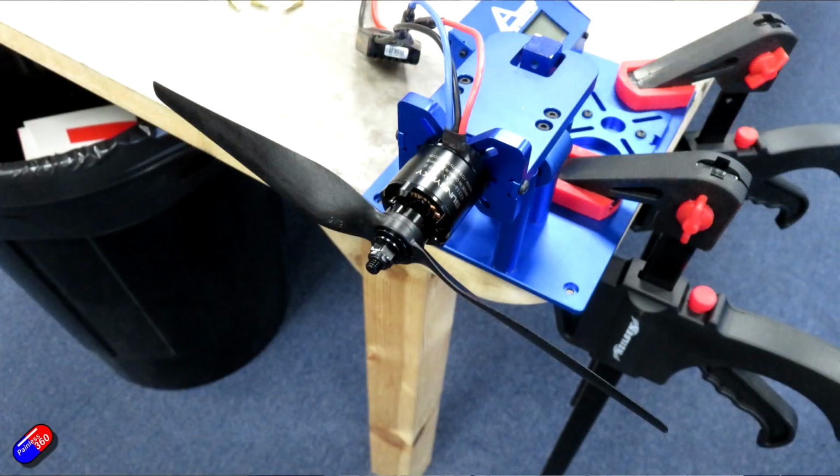There's no substitute for practical testing when you're playing with individual motors and props, because the data in the tables is more of a guide. Individual props will create different effects with a specific motor. So I can have an APC 9x5, an Aeronaut 9x5, a no-name 9x5 prop, put them on the motor, run and test them, and I will get completely different results. So you have to take some of the thrust data with a pinch of salt.